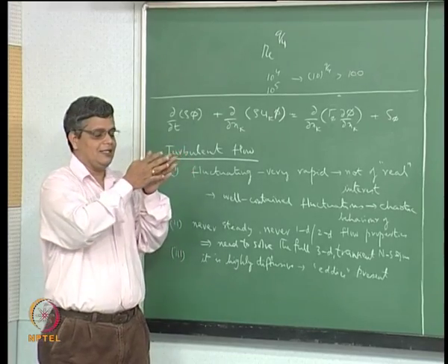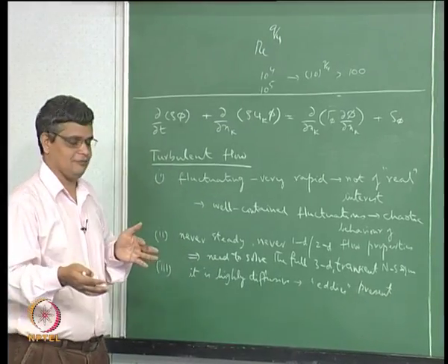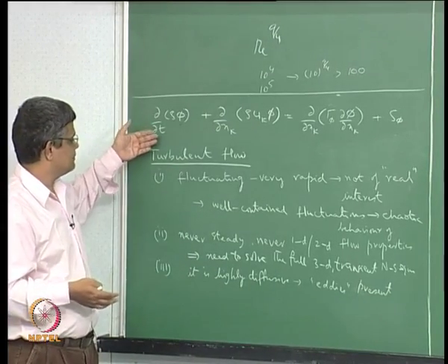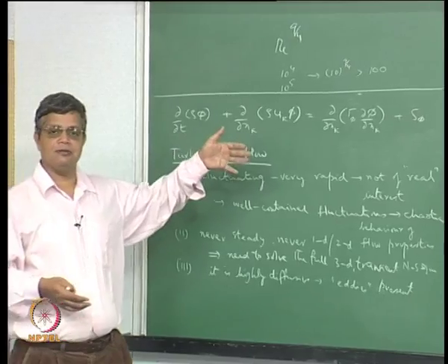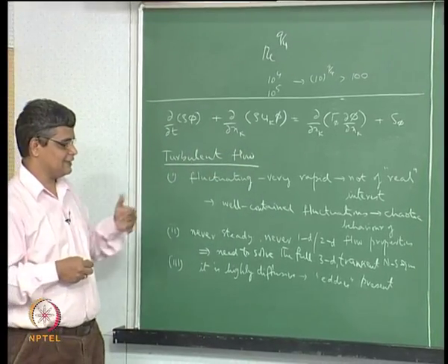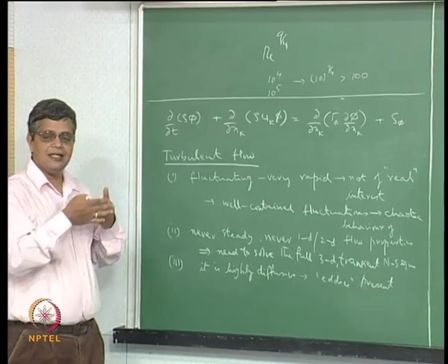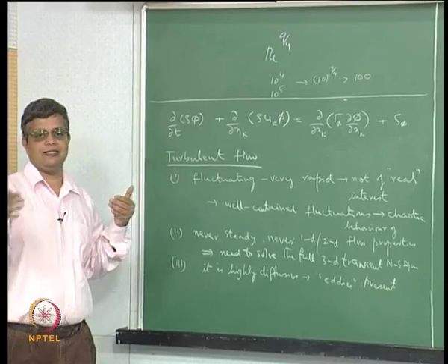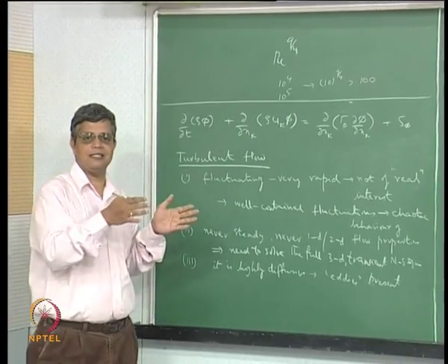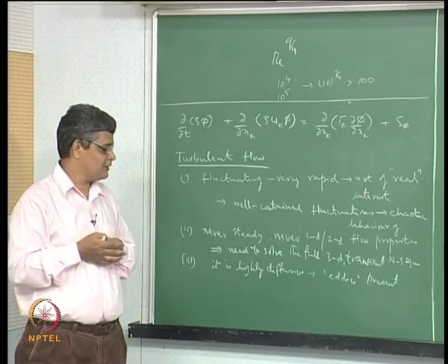So if one were able to visualize eddies, for example by going from time domain into the frequency domain, that is the usual mathematical way of looking at eddies and spectra and fluctuations, then one would find a continual range of size. It is not an eddy of a specific size, but eddies of several sizes, and a continuous range of sizes will be present.